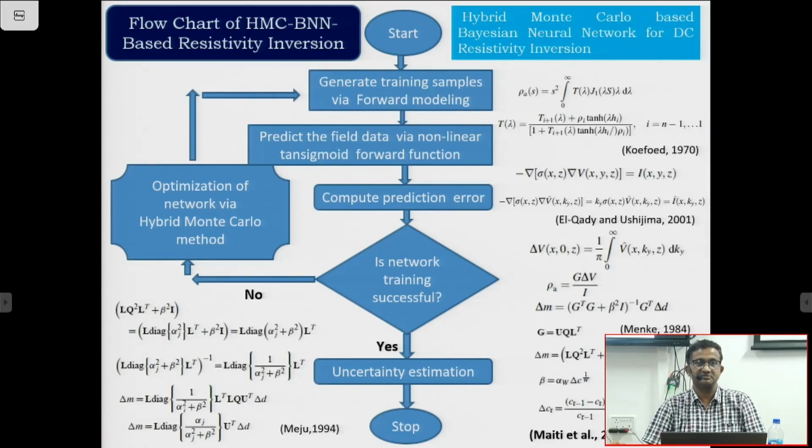In resistivity imaging systems, there are many commercial equipments. They inherited the concept of seismics of a bin size, and the combinations of your electrodes, like here current electrodes and potential electrodes, but in their system it is a multi-electrode system. Multi-electrode systems means the electrodes are interchangeable, so a current electrode can act as a potential electrode and vice versa.